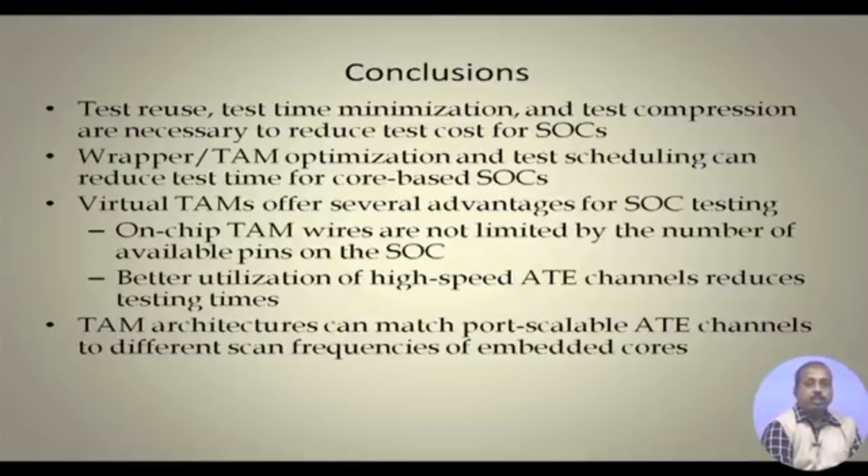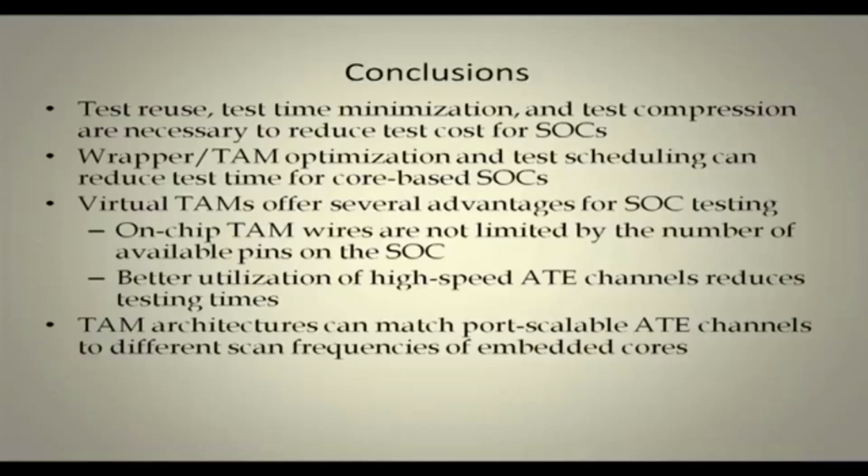Then the compression. Compression will be useful because the tester memory requirement will become low, and the transfer time of patterns from the tester to the chip will also get reduced. So, this compression is also going to help us in reducing the test time. Then there are wrapper or TAM optimization and test scheduling. So, this can reduce test time for the SOCs.